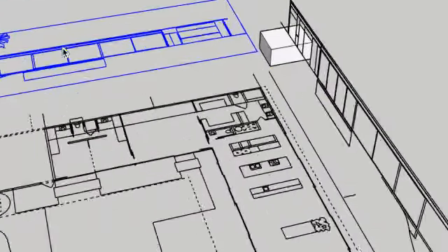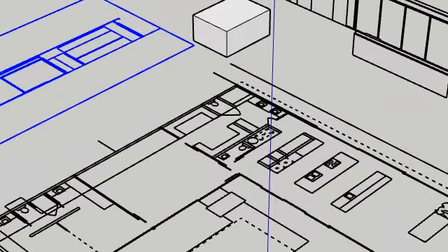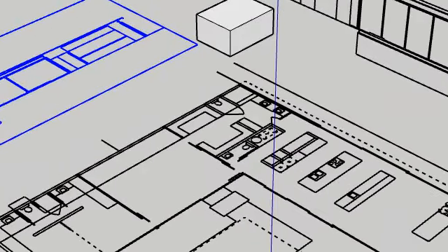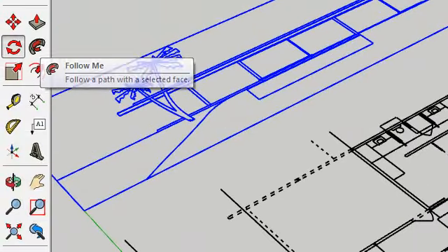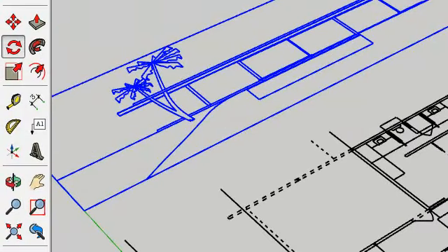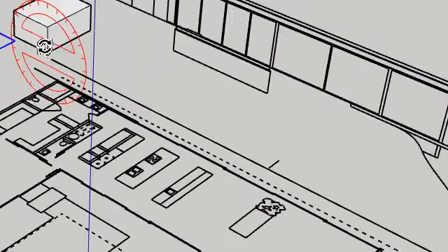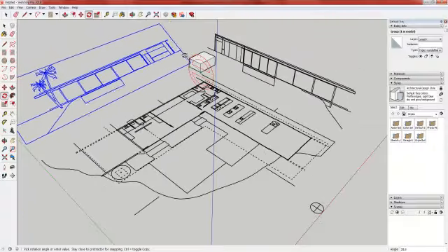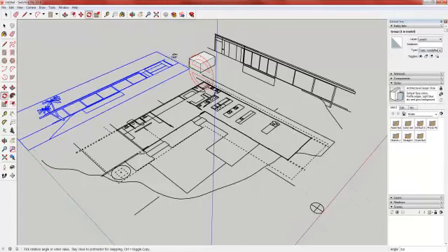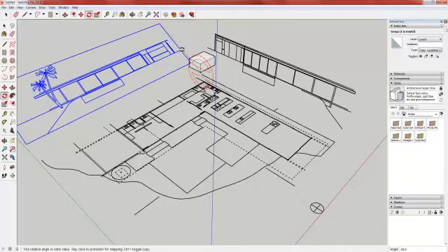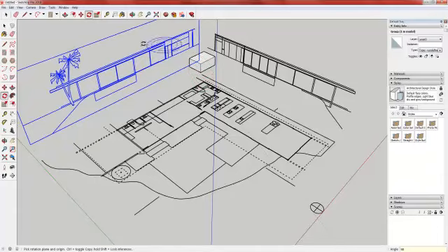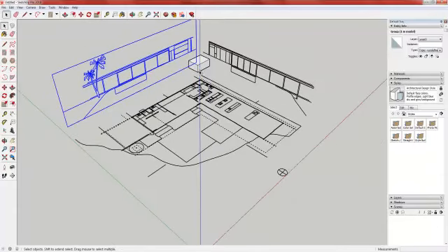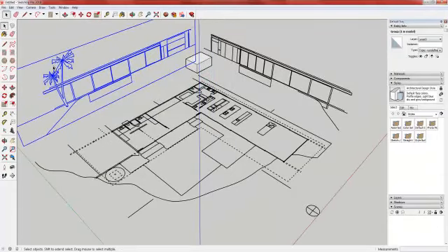Now I'm going to do the same thing with the other section. This time, the roof here needs to rotate up, so I'll use the rotation tool and the red axis. This time we'll be rotating around the red axis. Same type of thing: I'm going to set my base rotation, left click, and then left click again to set the angle, and you can see my line work starting to rotate up. I'm going to type in 90 degrees, and I now have my sections rotated vertically.